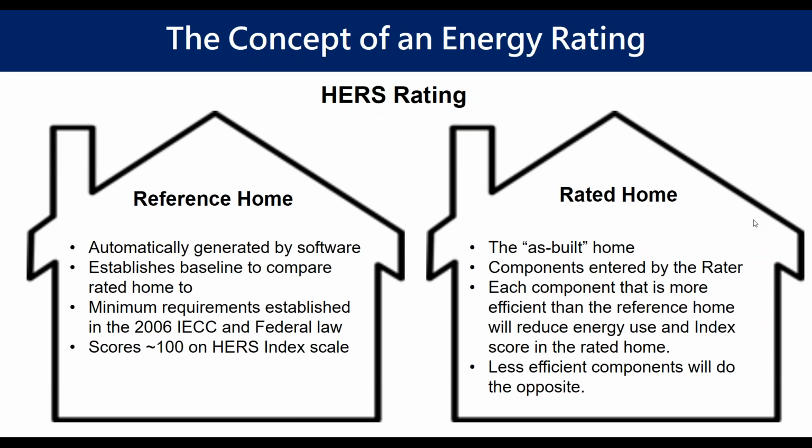The reference home is automatically generated by the software as the rater enters in the components of the rated home. The reference home establishes the baseline that the rated home is compared to. And as I'd mentioned, the minimum requirements for the reference home are established within the 2006 IECC and also federal law when it comes to equipment efficiency standards.